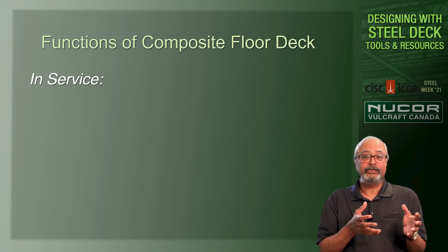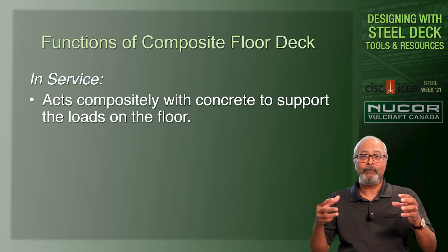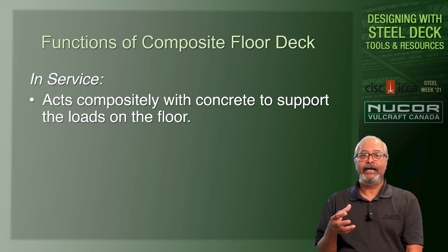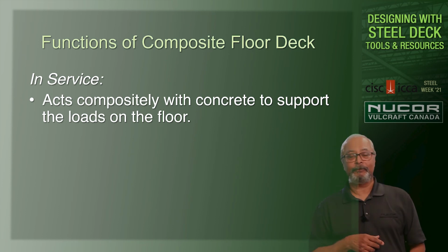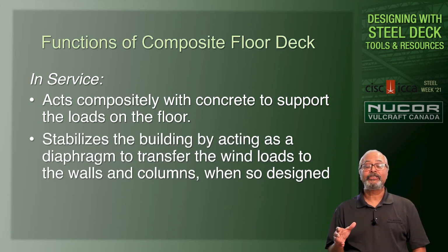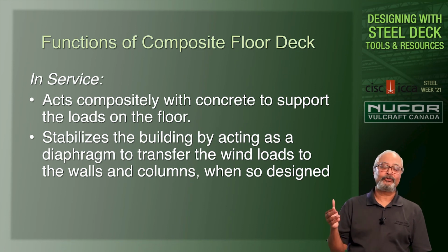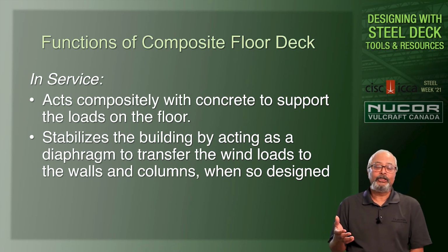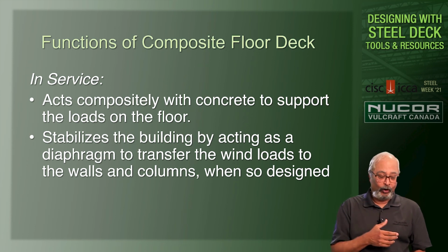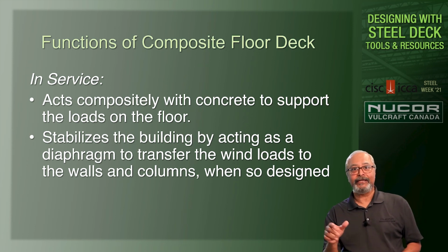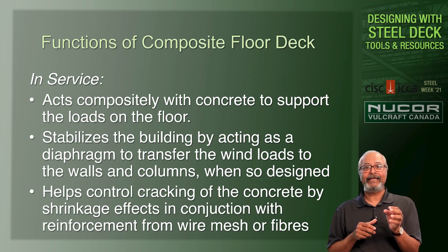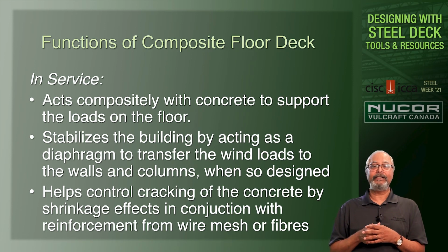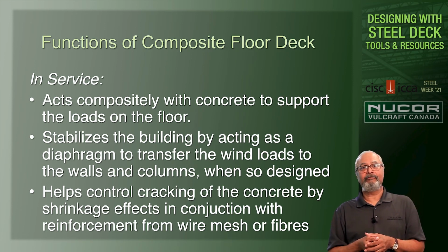And after construction, or in service, it acts compositely with the concrete to support the loads on the floor. It also stabilizes the building by transferring wind or other loads to the walls and columns when so designed. Often it also helps prevent cracking due to shrinkage of the concrete in conjunction with fibers or the wire mesh.